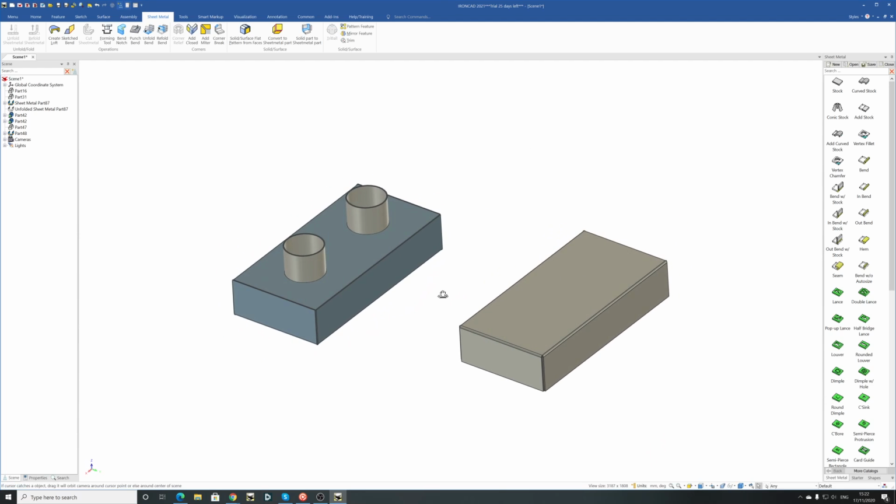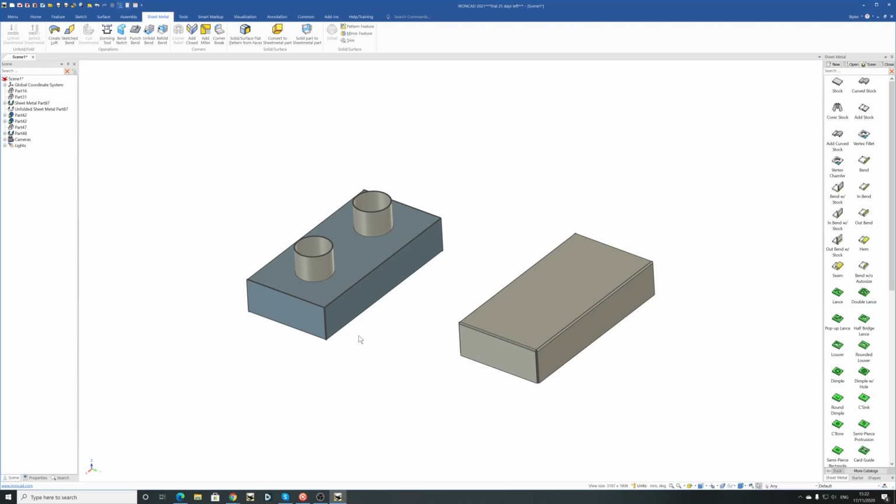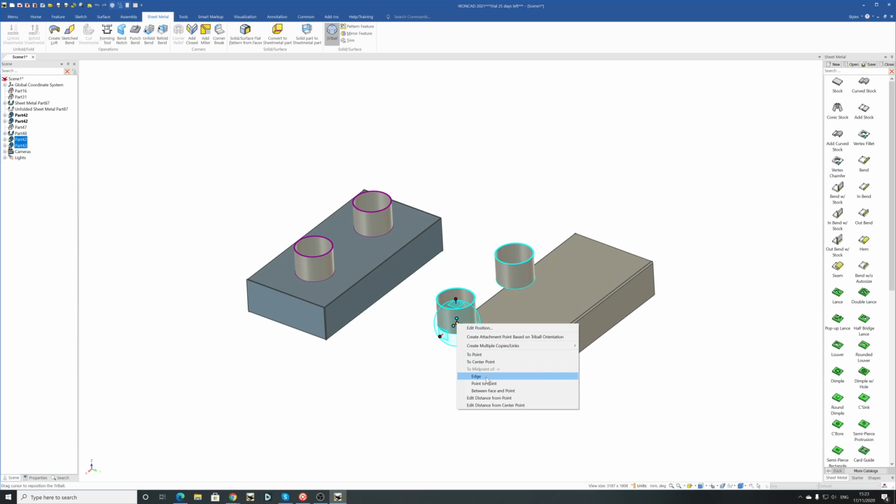So that's one way, and there's another way of creating that box. You need the holes to be put in there, so what I'll do is take these two and just copy them and put them over there. So the first thing I can do is drag them out. I'm going to link them, say OK, and this time I'm going to snap to point, middle of the edge.